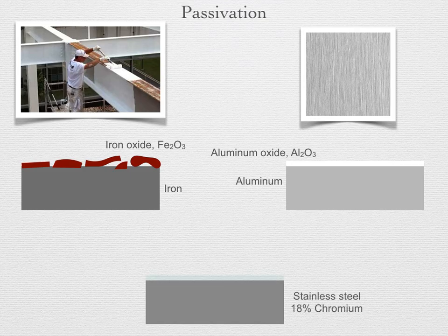On the other hand, stainless steel alloys of iron can develop effective passivation layers. The most common stainless steel is known in North America as Type 304, and is an 18-8 stainless steel, which means it's 18% chromium and 8% nickel. In particular, the chromium reacts with air and quickly forms a passivating Cr2O3 layer. It is self-healing in that a scratch quickly develops a new layer to protect any portion of the underlying substrate. The nickel is also helpful in the corrosion resistance, but chromium is seen as the most significant.